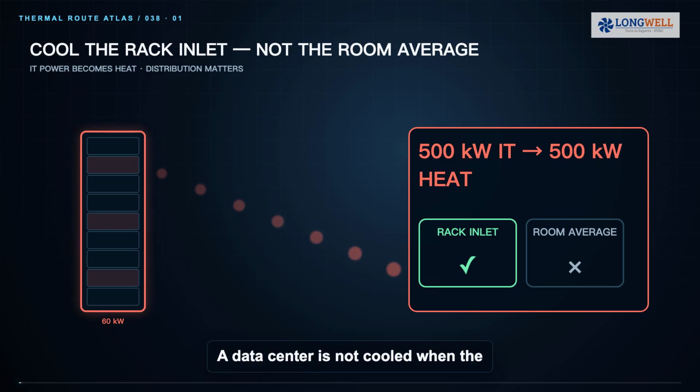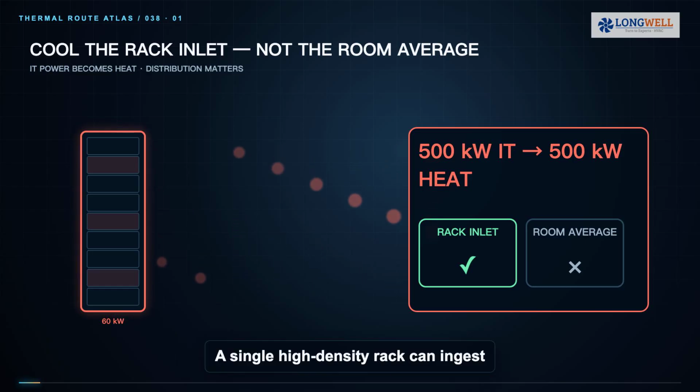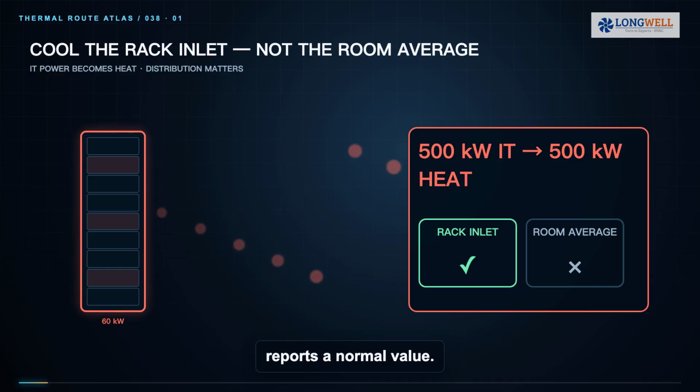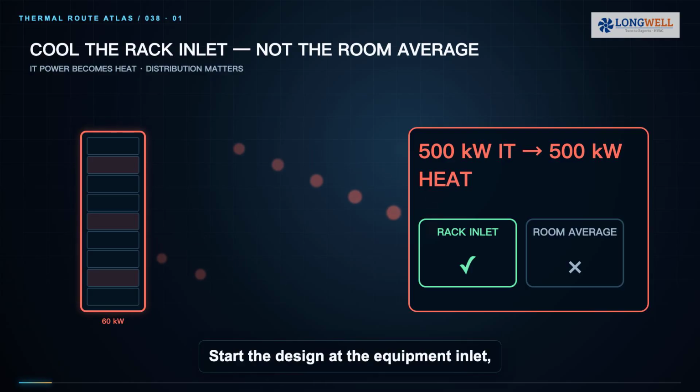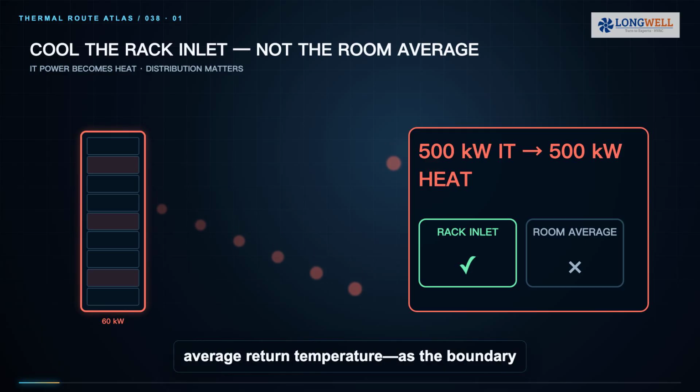A data center is not cooled when the room average thermometer looks comfortable. It is cooled when every server inlet stays inside the approved environmental envelope. A single high-density rack can ingest hot recirculated air while a wall sensor reports a normal value. Start the design at the equipment inlet, and treat the hottest inlet, not the average return temperature, as the boundary